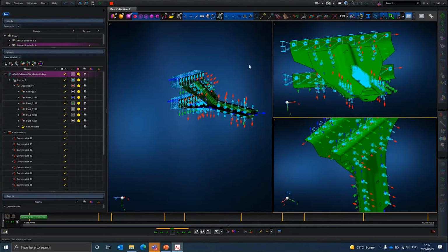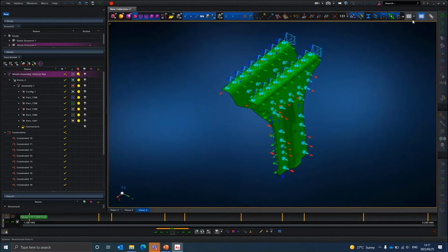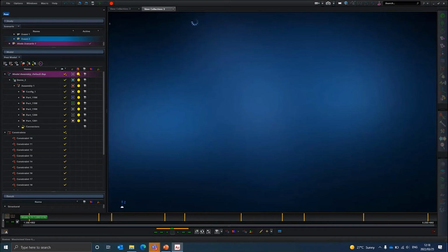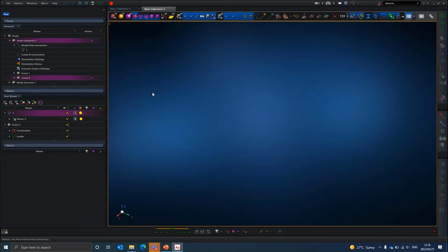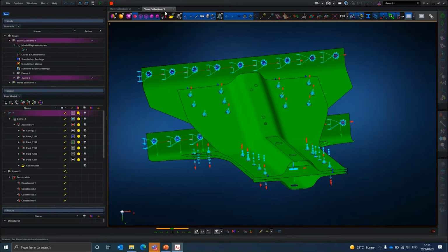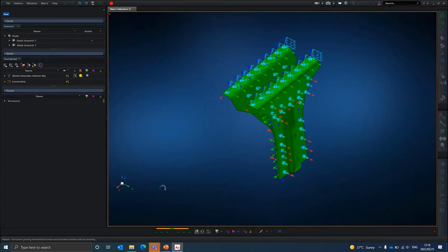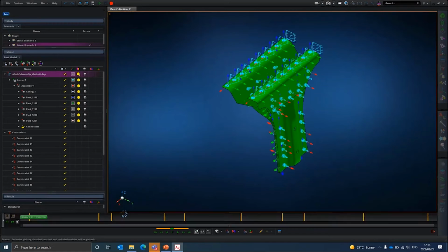The other thing that I also want to show here, let's just quickly move back to one screen now. So that's in terms of views. Then you also have this option of adding a collection. So a collection, again, is a new container. So I can also go and, for instance, say I want to plot event 2 in a new collection. And then it will open up a collection here. But now it's only event 2, and I can add, again, different views to collection 2. So you do have quite a bit of capability in terms of comparing results, plotting multiple results. For the specific case, I'll just stick to one collection with the 3 views that I have available.